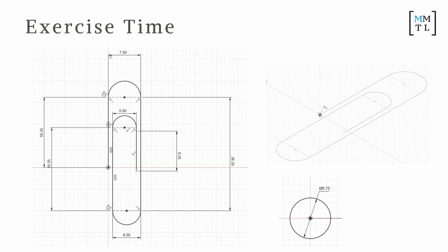Oh, I see. So everyone create the left sketch first, basically. Do the left sketch on the XY plane. Oh, okay. And the starting point should be on the origin.